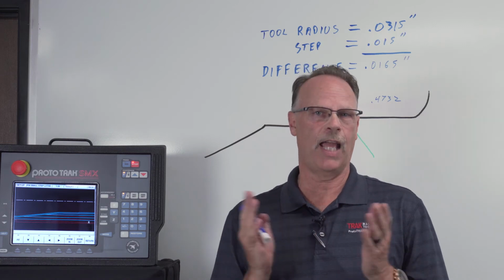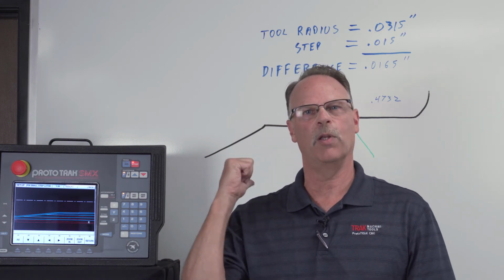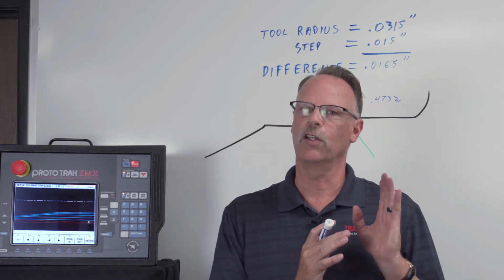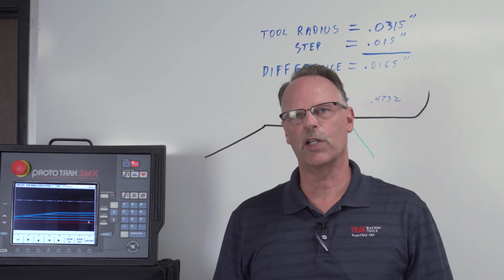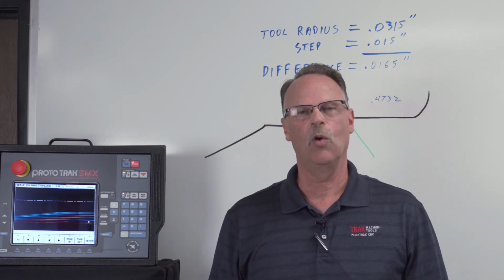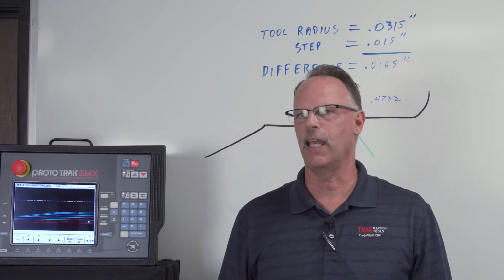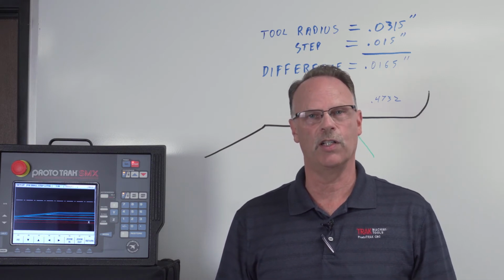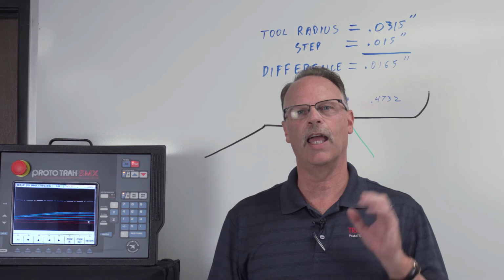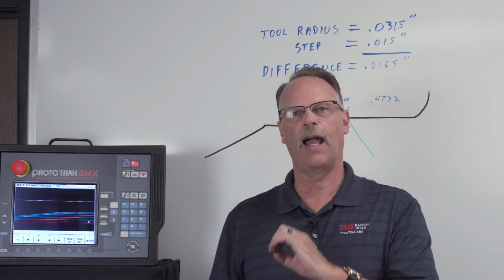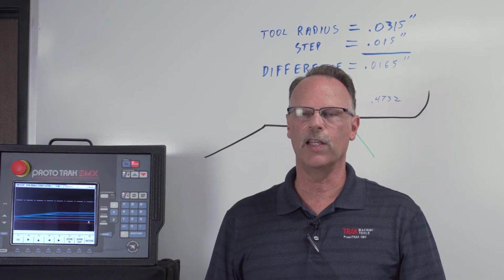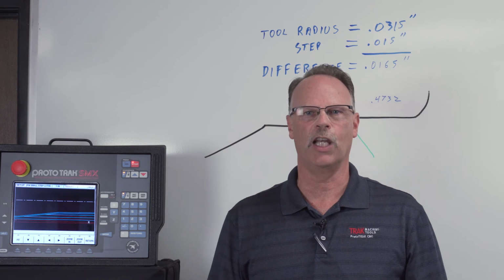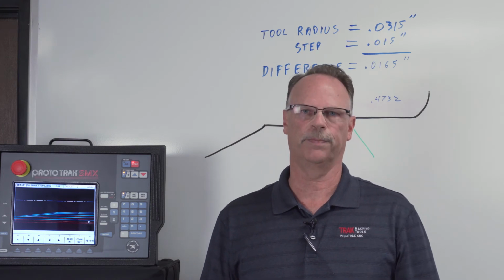So by using the Pythagorean theorem, you're actually going to be able to solve your solution no matter what size your step is and no matter what size your tool radius is. Now I'm going to show you another example of this in a minute using a milling machine, which a lot of times can be more difficult because I can never tell it that I'm using a 0 tool radius in the mill, if I'm using tool compensation at least. Okay, so I'm going to show you that, and then when you come back, after I show you that idea, I think you're going to have a much better handle on this, be able to use type 28, solve the solution right away, and get on to whatever you're machining. So I'll see you back here in just a minute.